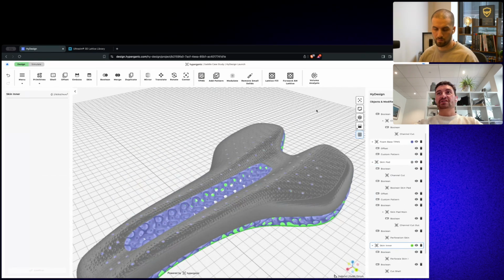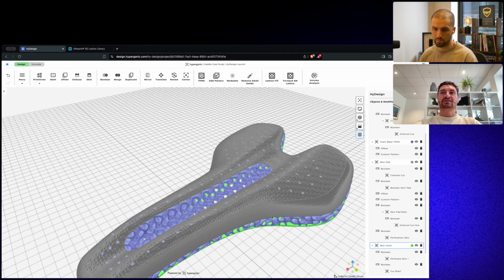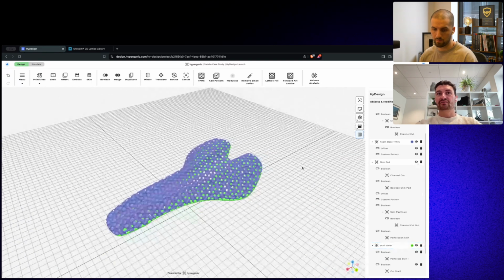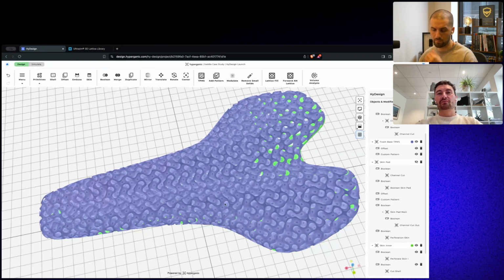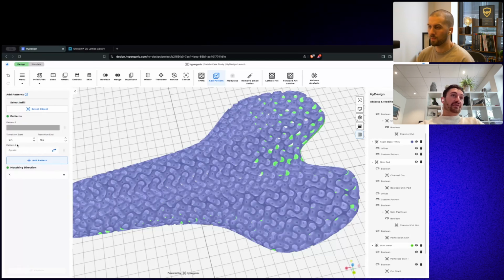And then, of course, I could do all sorts of other things to this gyroid. I'll quickly unview the skin pad on the top. Let's say I want this gyroid in the back, and I want another TPMS in the front. So I'll merge this, as I was showing before, into, for example, a sports diamond again, and I will use this infill.